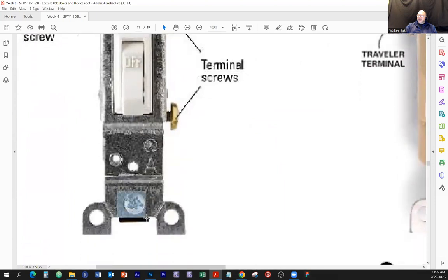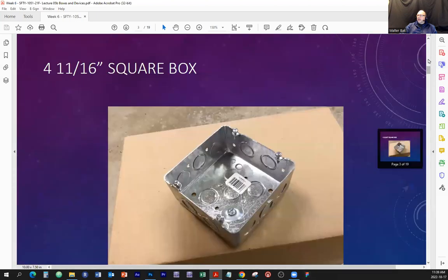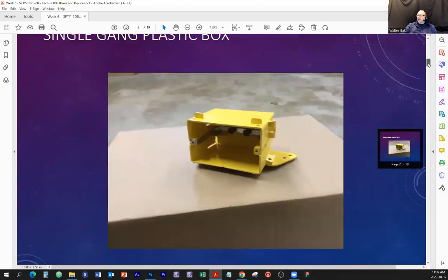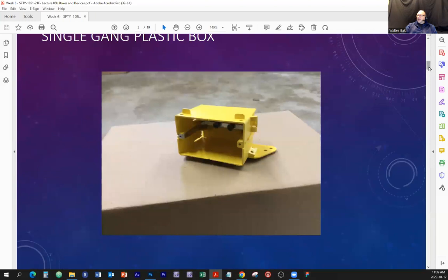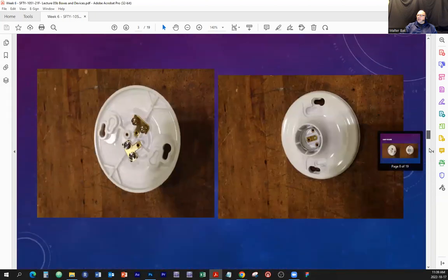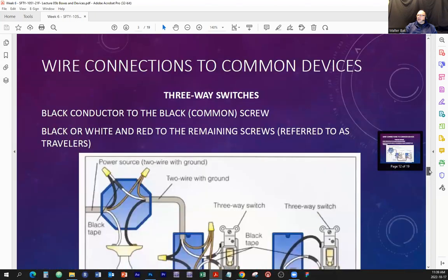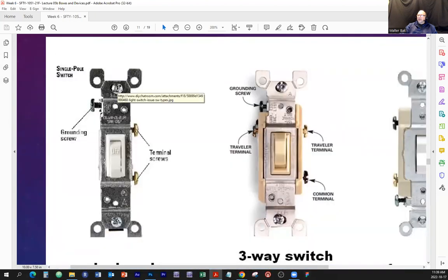and there's another, this mounting screw right here, would connect to the bonding terminal on either of this plastic box, or if this whole box were all metal, then yes, it would still connect to the box. So in this case, there's no need to have that extra bonding screw because, well, the connection is being provided physically and is being fastened by this screw.